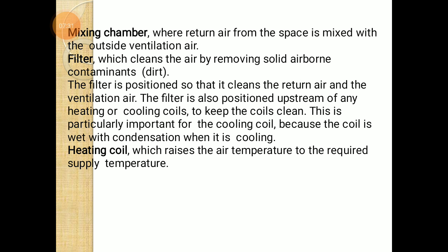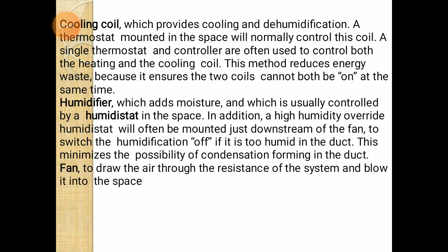Mixing chamber, where the return air from the space is mixed with outside ventilation air. Filter, which cleans air by removing solid contaminants. Heating coil, which raises the temperature of air up to the required supply temperature. Cooling coil, which provides cooling and dehumidification. A thermostat must be mounted in the space, which will normally control this coil.